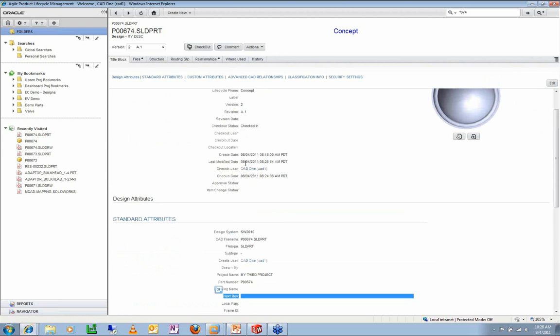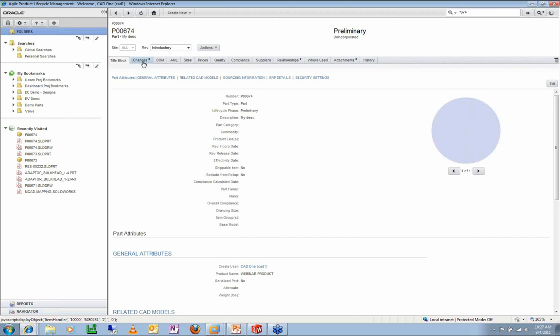It'll publish the next revision sequence, and the reason is that a lot of companies presuppose the drawing revision and put that on the change order before it's actually released. So they know it's going to become revision B. They want to assign that to the title block of the drawing, and they want that next revision field to be used to pull the information into the title block of the drawing. So in the change order, when I go through this, we'll see that actually transact.